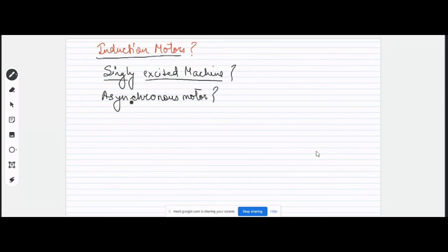Yeah, right. Basically, we call it an asynchronous motor because your motor doesn't have the capability to rotate at synchronous speed, right? It cannot operate at a synchronous speed. Your induction motor cannot operate at a synchronous speed. That's why we call it an asynchronous motor. Now the question will arise, why there will not be any torque or force, meaning why it cannot operate at a synchronous speed?